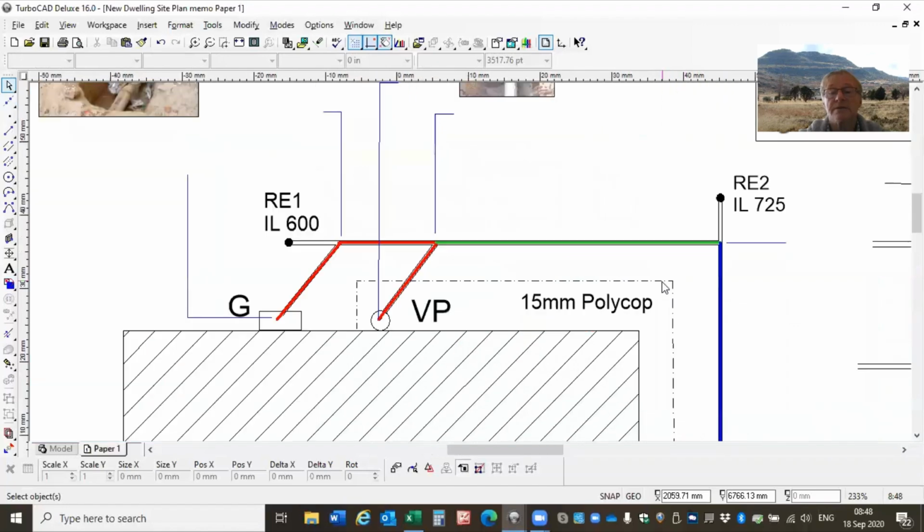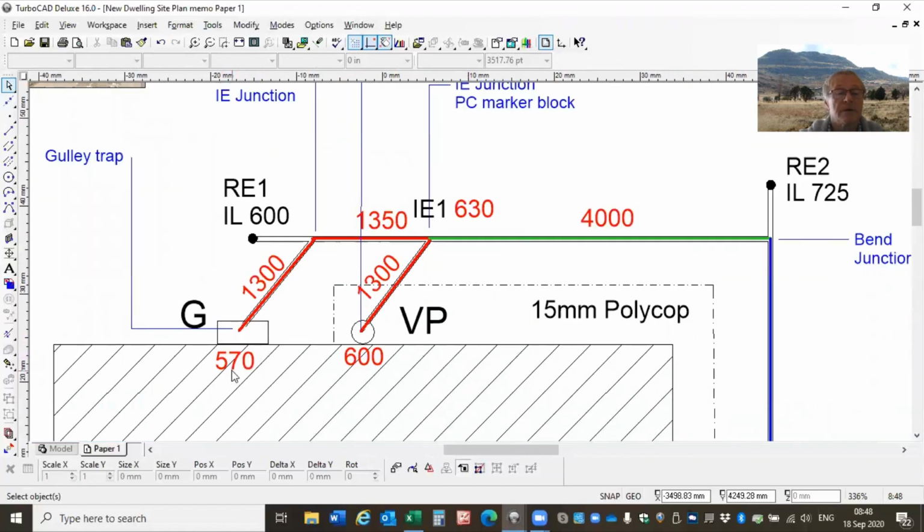If you look at our gullies, that gully, the depth there is 570 millimeter. Sorry, just by the way, how did I determine that depth? I've just used that depth of 600 millimeter at that point, at a fall of 140 millimeter, so the depth at that point there is 570. You can do the calculation. I've used 1 in 40. Similarly, for that one, the depth there is 630. And at calculate, it gets a depth there of 600 millimeter.